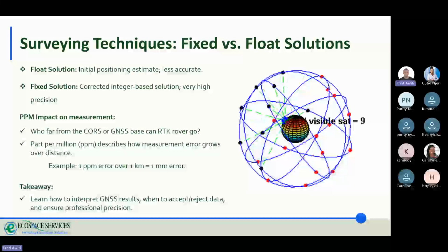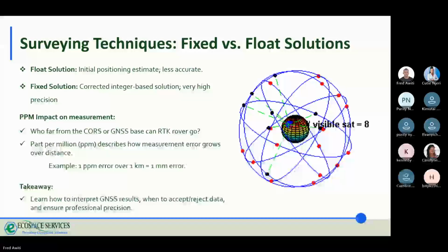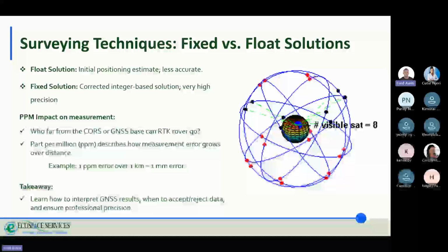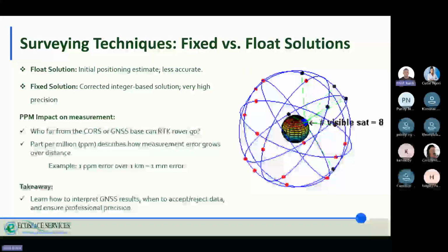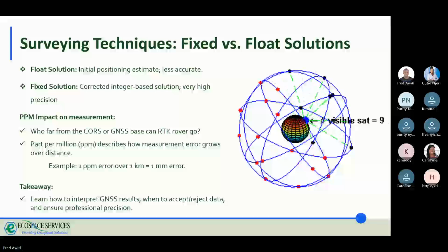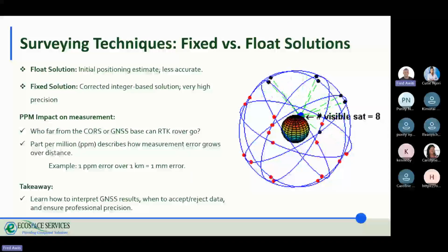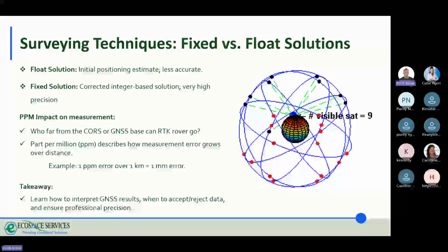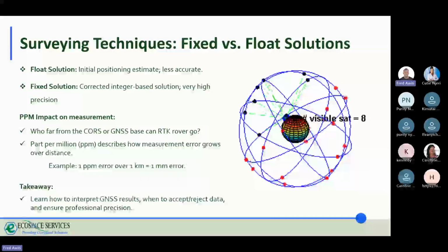In essence, what I'm trying to say is, in the GNSS receiver, we only have a motherboard. So we do not calibrate GNSS receivers. There's something called the antenna phase center, which is what is just being worked on to ensure that these errors that we are talking about here are reduced to the bare minimum, as recommended by the manufacturer.